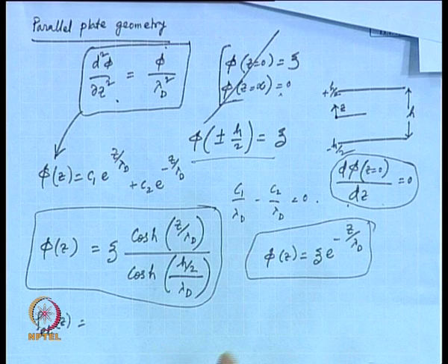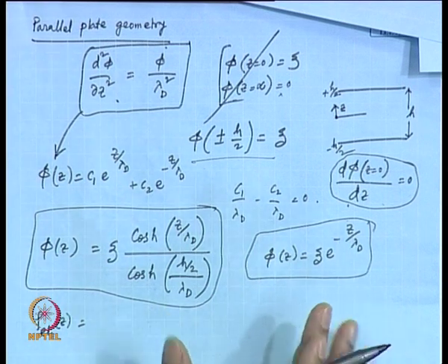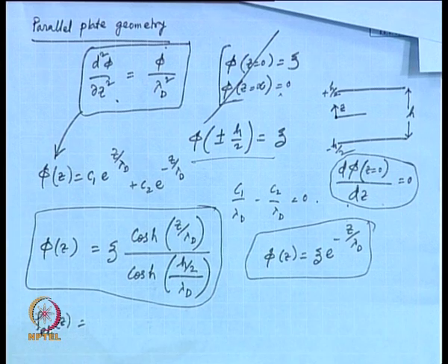So, you must have seen the thought process here. You have defined a potential, you have to come up with a rho E L, which is basically the charge density, and then you introduce that in the body force term in the Navier-Stokes equation, and only then can you come up with an expression for velocity, the electro osmotic velocity. This is the velocity you can expect in electro osmosis for a channel formed between two parallel plates.